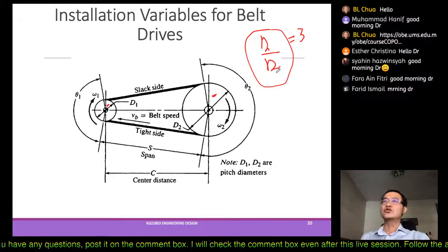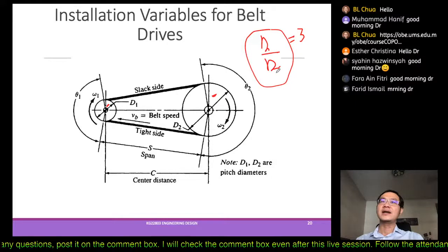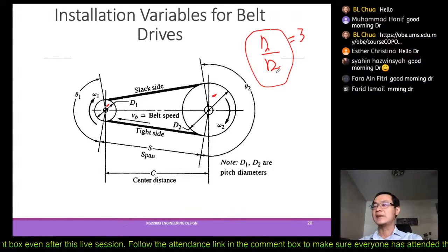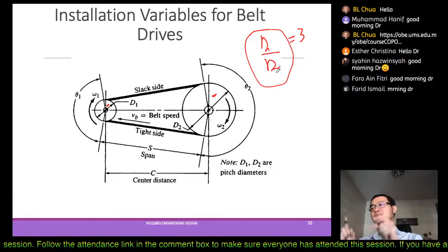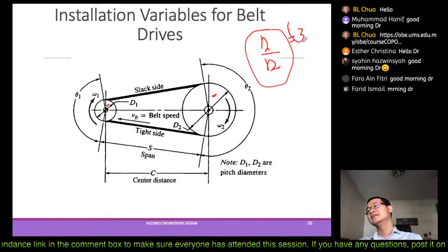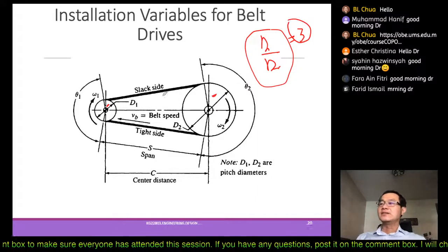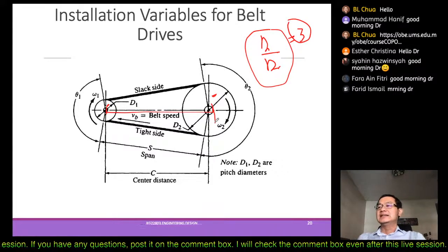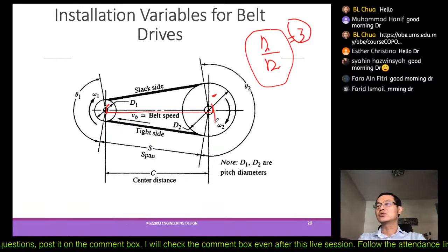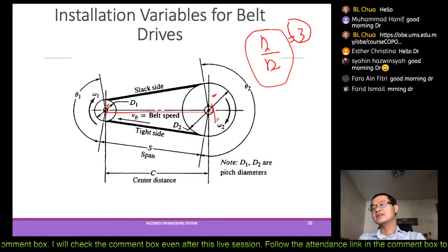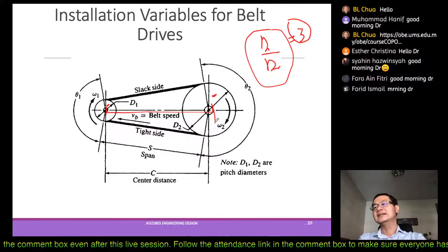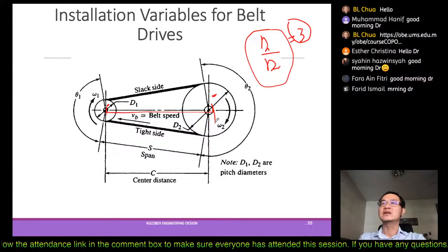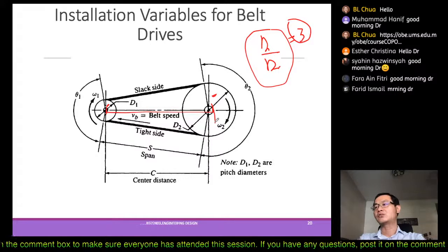So you have to try and error from the manufacturer's shaft or pulley diameters. You just find the best combination between these two to get the 3. Then from there you also have to know or estimate the distance between those 2 pulleys. If this is too long, then you may need to compound it with another set of belt drive.